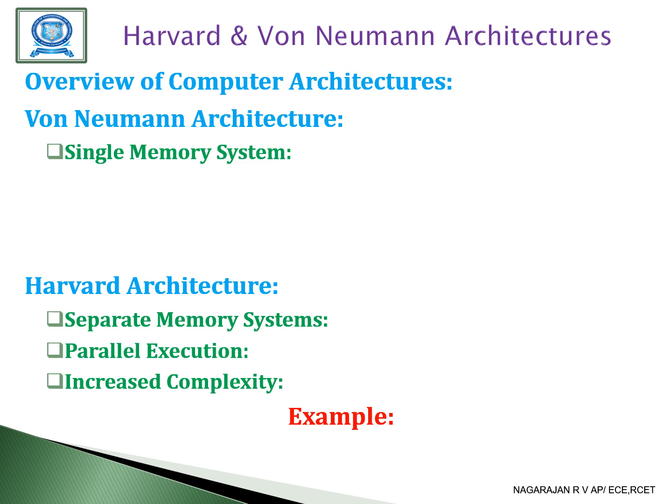The processor fetches instruction and data from the same memory one at a time using a single bus system. Sequential execution: instructions and data cannot be accessed simultaneously because they share the same bus. This leads to a phenomenon known as the von Neumann bottleneck, where the CPU is idle while waiting for memory operations. It will do one operation at a time. Despite this limitation, the architecture is simpler and more cost effective, making it popular in general purpose computing systems.